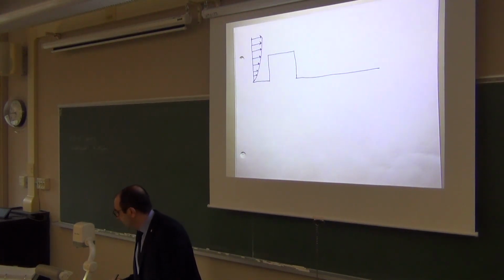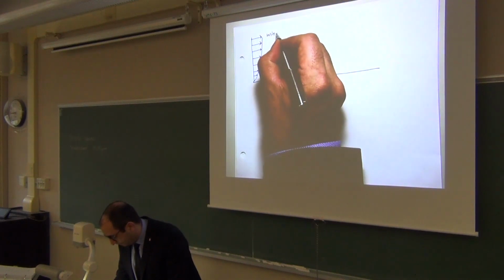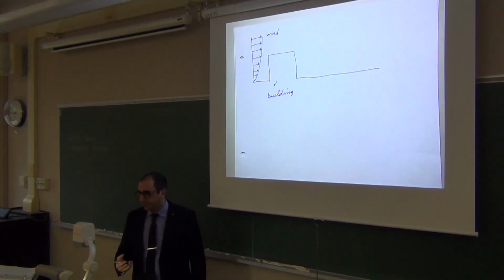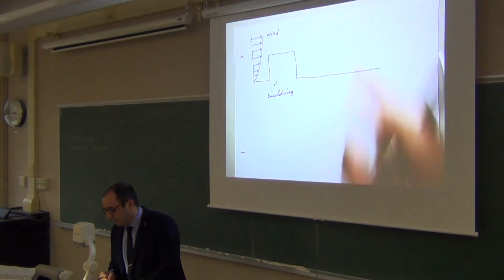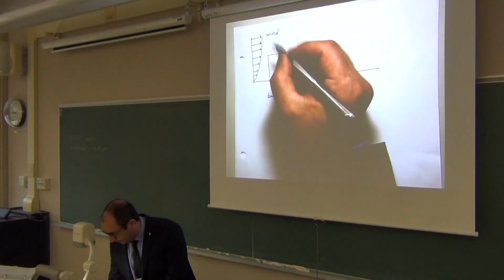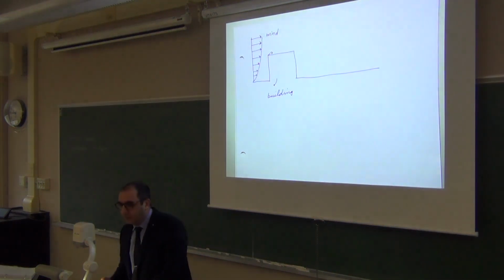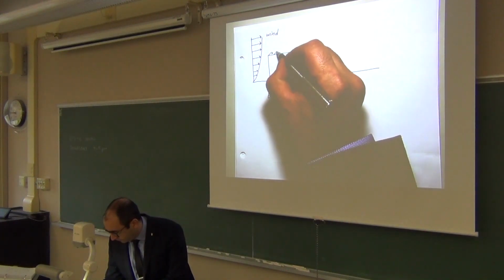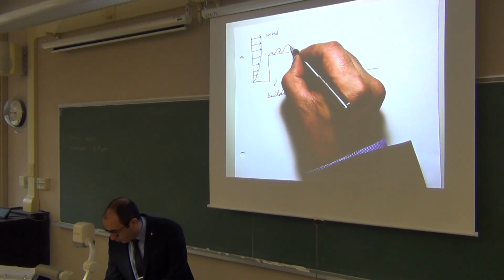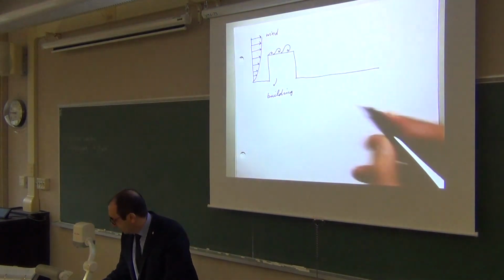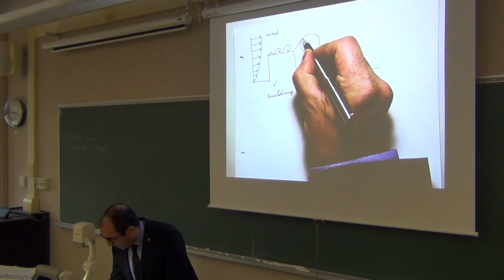So what's going to happen? Well, the wind hasn't approached the building yet, right? Like here it's all stagnant. The air is not moving. But the wind gradually approaches the building and starts interacting with it. One thing that happens is near the edges and surfaces of the building, eddies start to form. Okay? Now, let's say this edge of the roof can form an eddy, and in fact, this eddy will grow in size. In fact, it generates a shear layer in airflow around this building. But finally, you have an eddy that's big enough for our purposes.